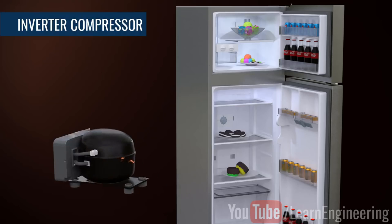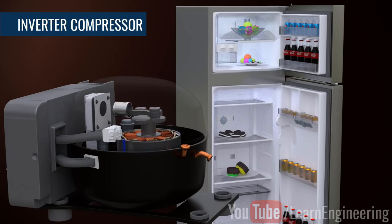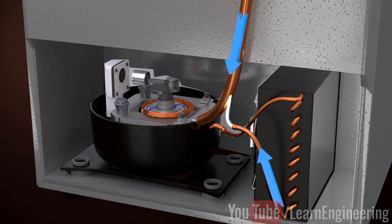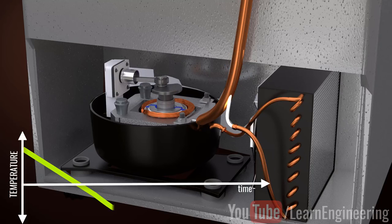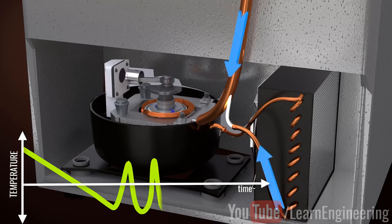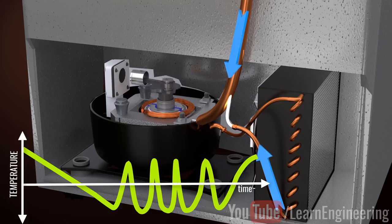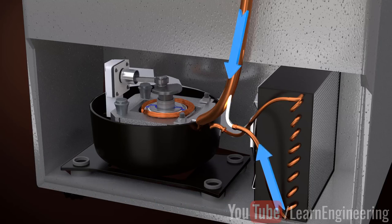Digital inverter compressors. A compressor is the heart of any refrigerator and is the device that gives life to the whole system. You might have noticed that the compressors in old refrigerators will either be on or off. This is a single-speed technology. When the inside temperature of the refrigerator reaches an optimum level, the compressor will be turned off. When the temperature goes above a certain limit, the compressor will be turned on. So you can see that the temperature control inside the refrigerator is not smooth. Moreover, such abrupt speed variation of the compressors will lead to durability issues for the compressor components.